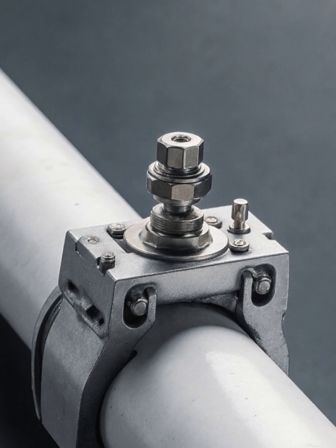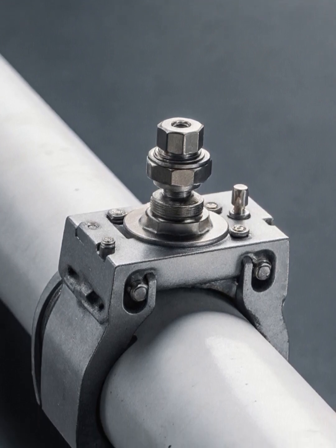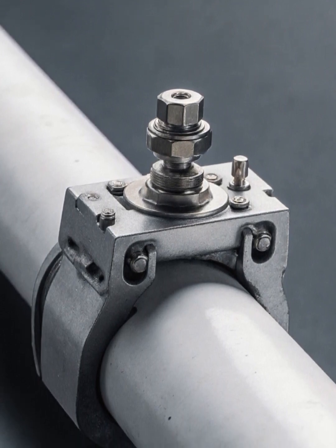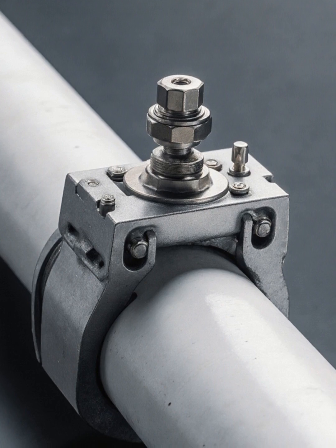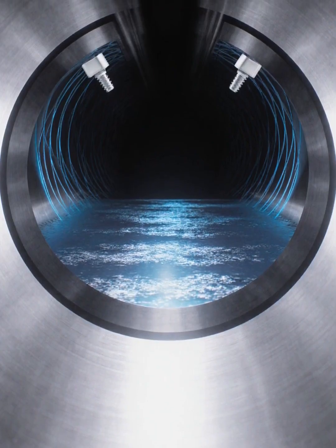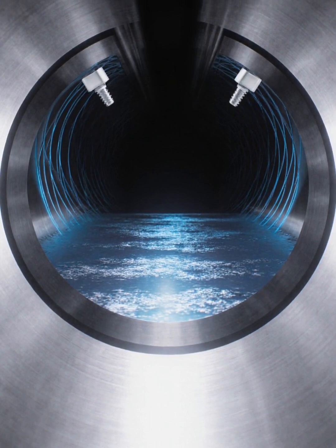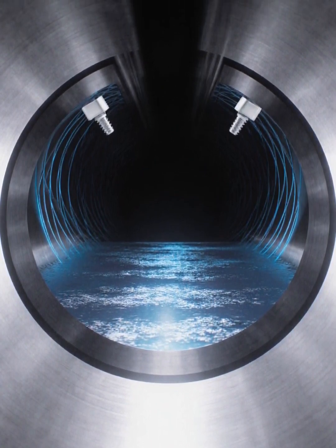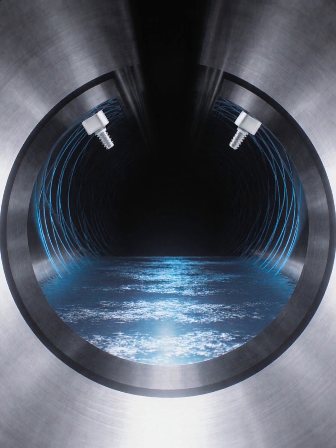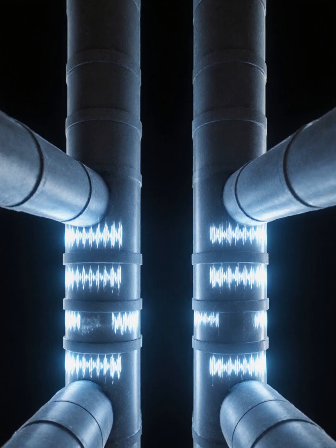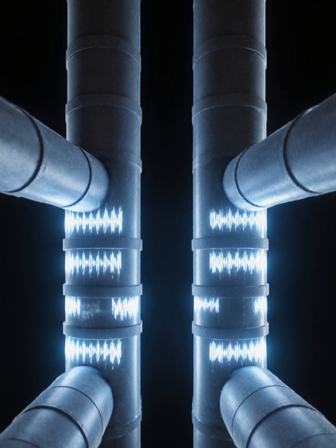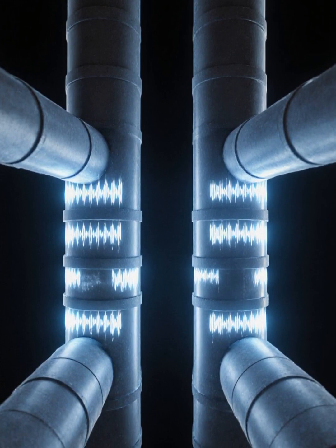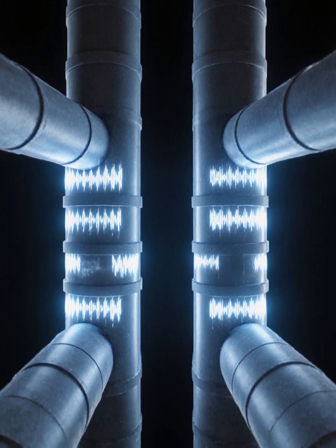The transducers are clamped on the outside of a closed pipe or inserted in the pipeline by using an isolating ball valve assembly at a specific distance from each other. Transit time flow meters measure the time it takes for an ultrasonic signal transmitted from one sensor to cross a pipe and be received by a second sensor. Upstream and downstream time measurements are compared. With no flow, the transit time would be equal in both directions.